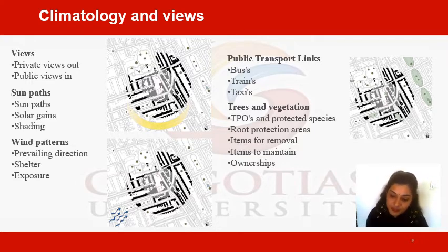When considering local weather patterns, the aim should always be providing a building with the best possible access to solar gains, daylight and shelter. This can be achieved through calculated control of the effect of sun, wind and rainfall, through good positioning of openings and roof lines to provide natural light, warmth and shelter throughout the year. To cool a building, its orientation can pull and circulate cool summer air through its plan by aligning its long axis with the prevailing wind direction, and by providing overhangs for shade. Built volumes can provide shelter and create protected external spaces via courtyards.